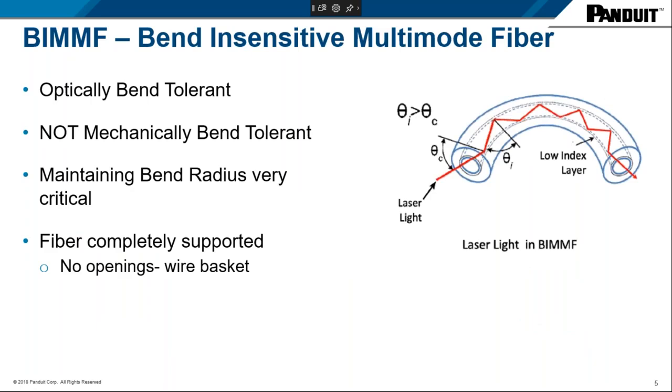And then I want to dive into bend insensitive multimode fiber. With this, there's a perception that you could take a fiber cable, you could bend it around a pencil, and that's fine, but I do want to highlight that it is optically bend tolerant, it is not mechanically bend tolerant. So it's not recommended to take that cable and bend it the way it's sometimes showcased, where the cable is bent around a pencil. It's important to maintain proper bend radius control.